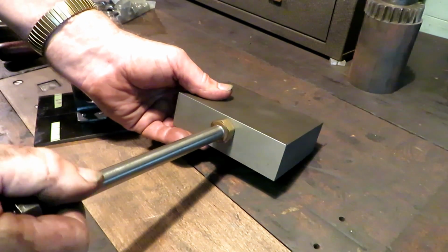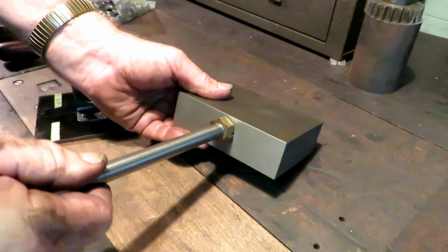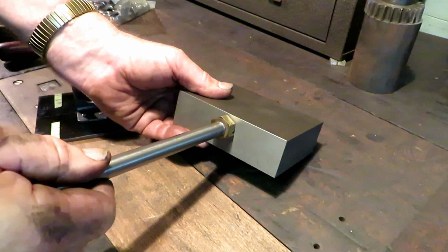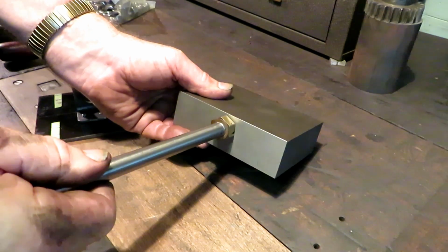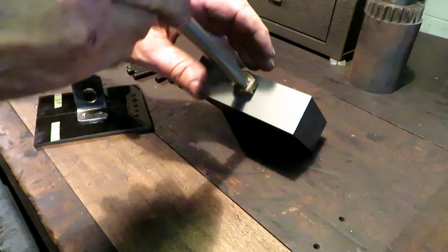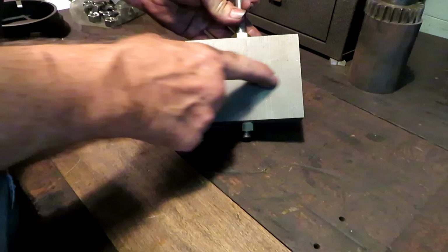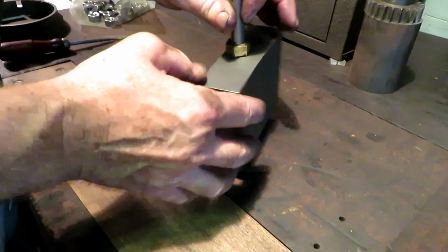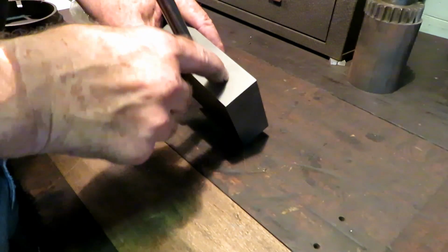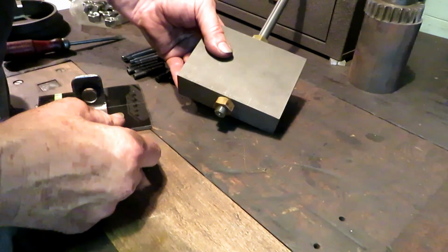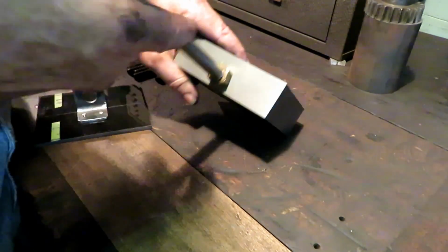I think the fit in the hole is about right. I may have to open it up just one more drill size, but you can do that anytime. Next time I'm gonna surface this in the shaper and start lightening the profile and test fit it in the engine.